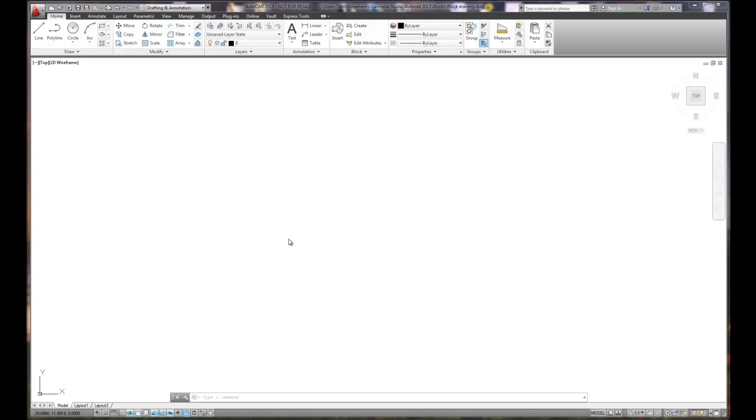And yes, you could actually use Microsoft Access and dBase and other database, FoxPro database tools and link that information into your drawing environment. That is a possibility. We're not going to get into that in this particular video, but I just want to make sure you understood that the advanced side of blocks and attributes is to actually use a database tool and link the data to your drawing. You can also do it with a basic Excel spreadsheet to start off. But in our case, we're going to use the internal tools that Autodesk provides, which is blocks and attributes.